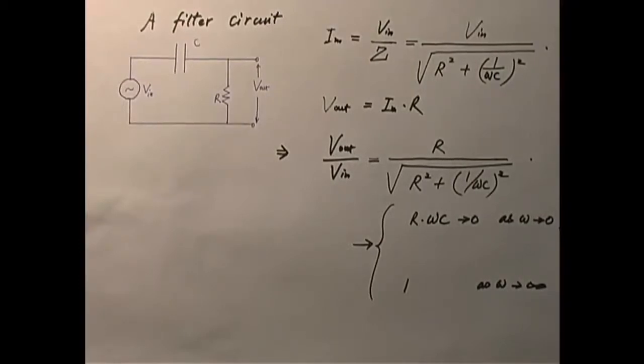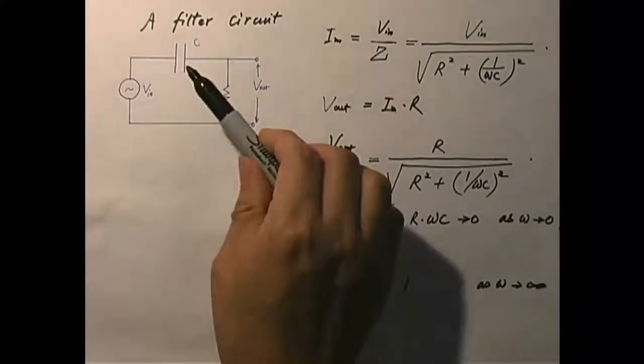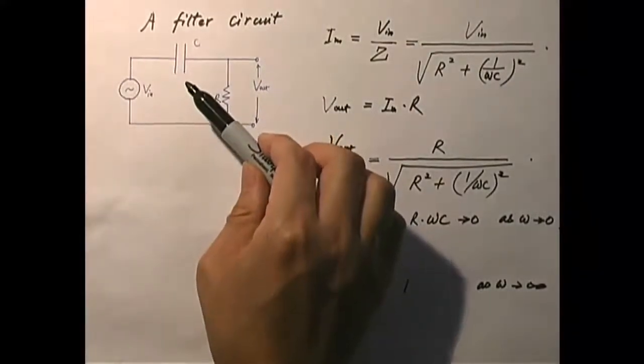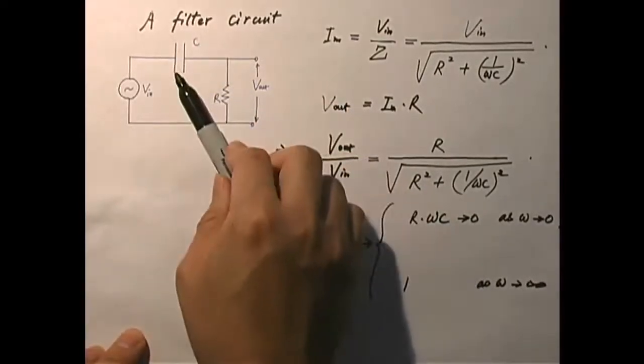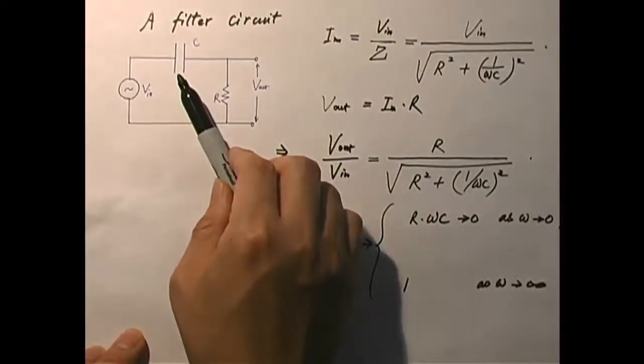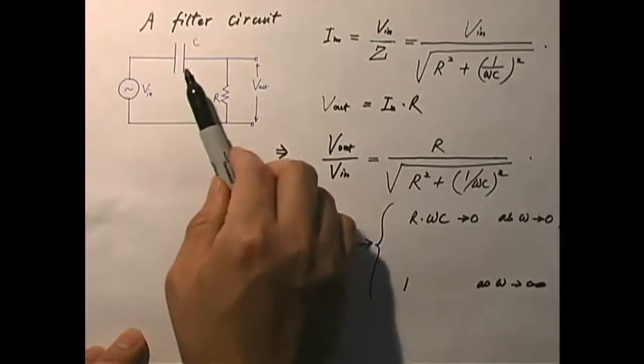You can also design a filter that filters out high frequency signal. Guess how do we do that? Instead of capacitor, what do we do? You probably have guessed. Yeah, put an inductor here instead. Because the inductor doesn't care about low frequency signals. It just lets them pass as if it's just a wire. On the other hand, if you try to drive a very high frequency signal through it, it's unhappy.